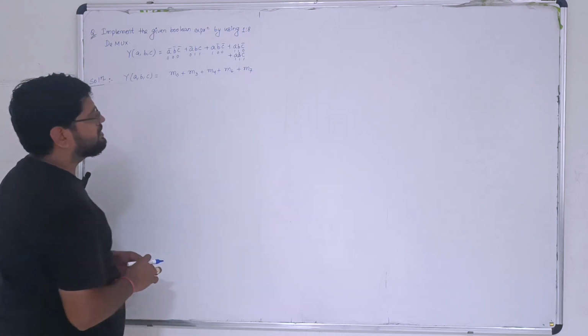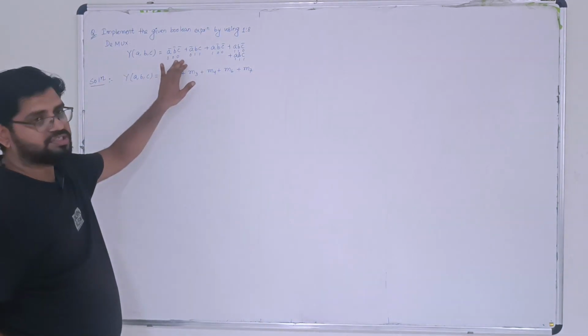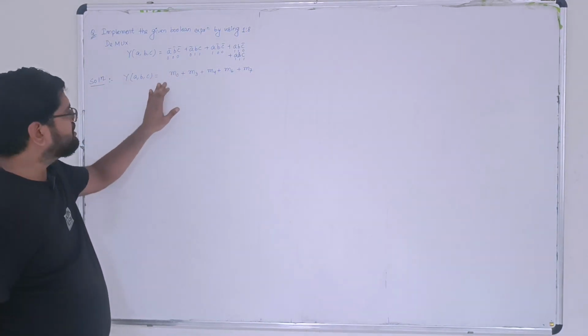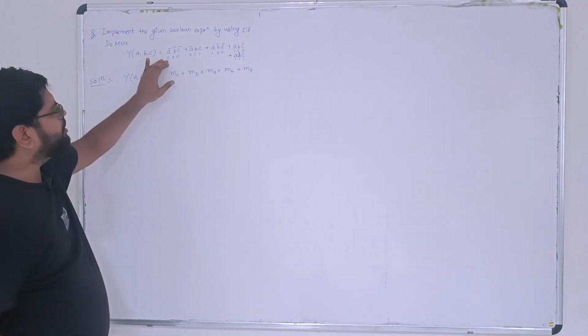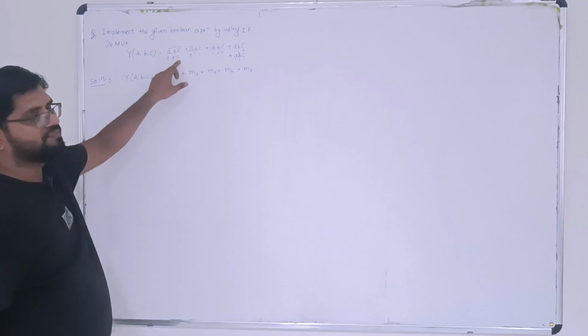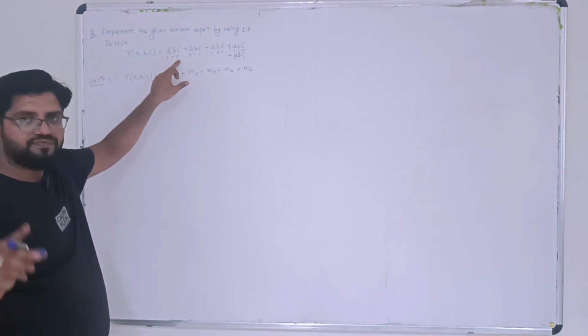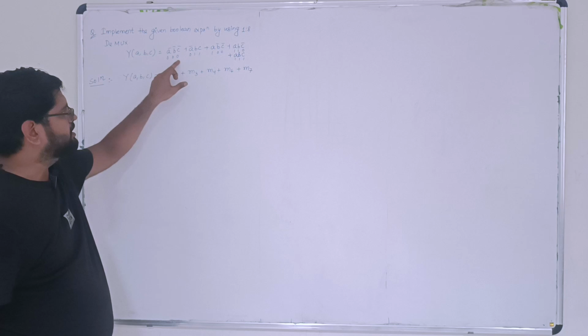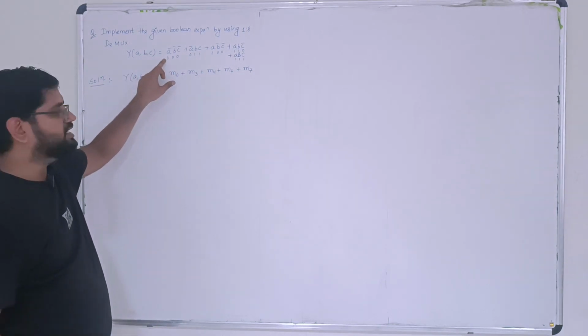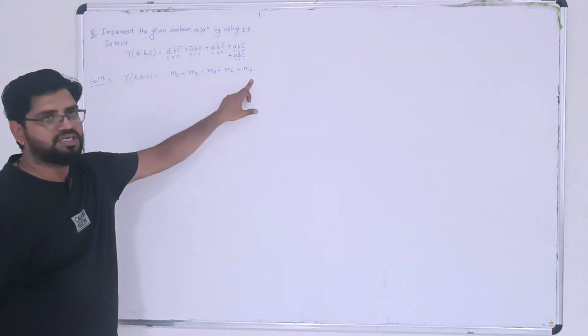So this is the first step that you will do. Whatever Boolean expression that is given to you, convert that into the min term summation. Now, sometimes it might be a possibility that the question will not be in a standard form. So the first step in that case will be to convert the given Boolean expression into standard form. Once that is converted to standard form, we'll be able to get the min terms.